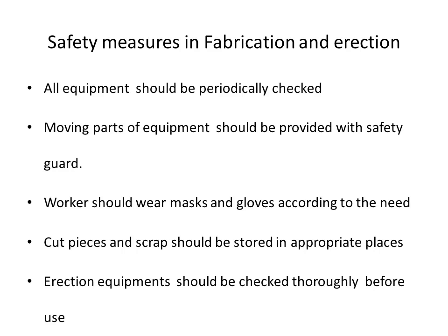This is very much important because if any equipment gets damaged in between the work, it will result in huge accidents. While lifting, if the load is half lifted to a certain height and the instrument gets damaged, there is every chance that the lifted material, which may be very heavy or some large equipment, will fall down immediately, resulting in huge accidents. So we should ensure that all lifting tools are checked thoroughly before erection.